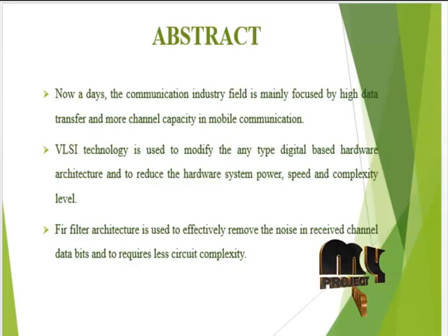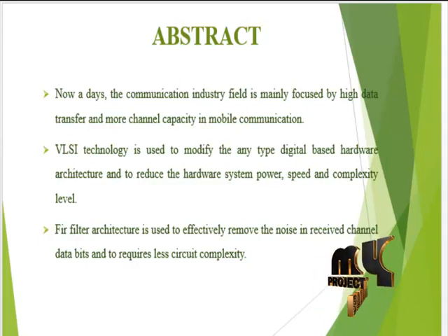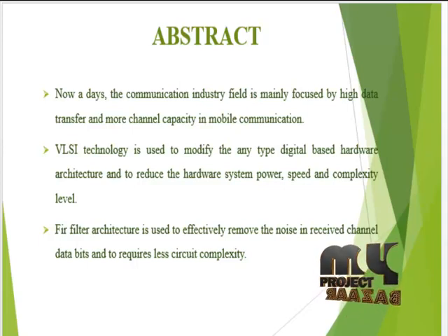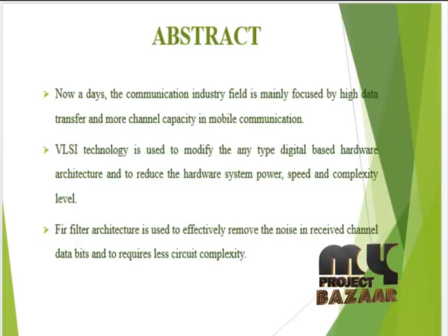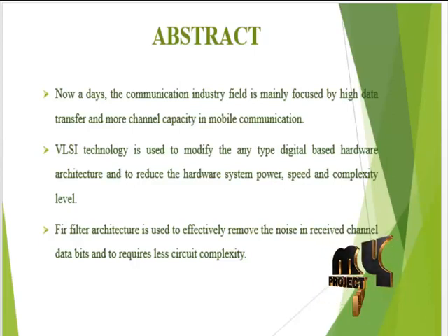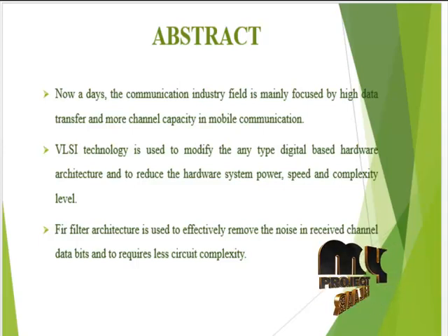Based on the novel implementation of the product accumulation sections of FIR filters, the existing delays due to the structural adders can be integrated with the MCM multiple constant multiplication process and the block together to further reduce the critical path. The delay caused by the structural adder can be completely eliminated, and the experimental results show a significant reduction in the critical path and the cost of the process.